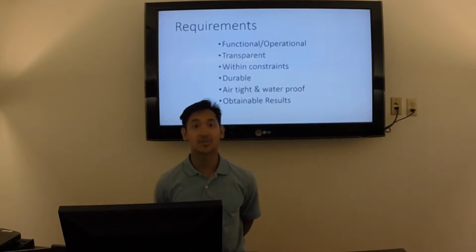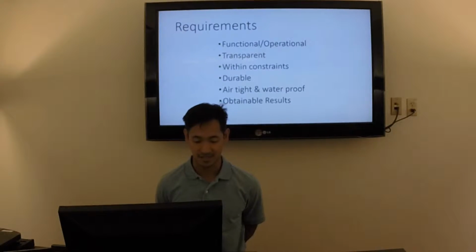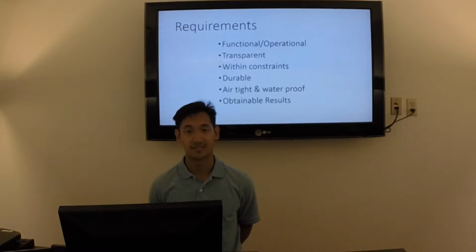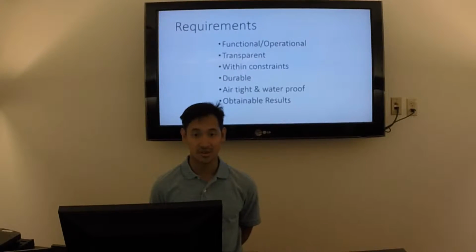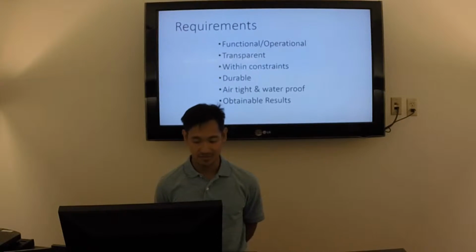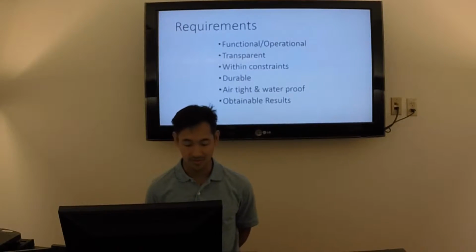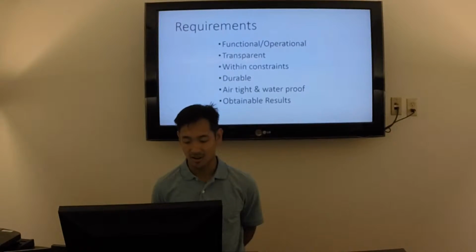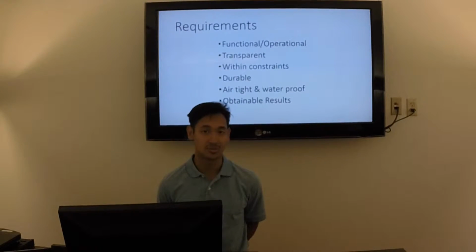Hello again, and now I'm going to be talking to you about the requirements that our group will face proceeding with this project. The transparent gas lift valve, or TGLV, must be diverse and operational. It has to be able to function as an actual gas lift valve and to perform its duties during a gas lift operation. The valve must demonstrate how energy from a charging chamber will build up and open the valve, releasing gas or fluid into the reservoir, creating an artificial lift to help with the production efforts in a downhole operation.